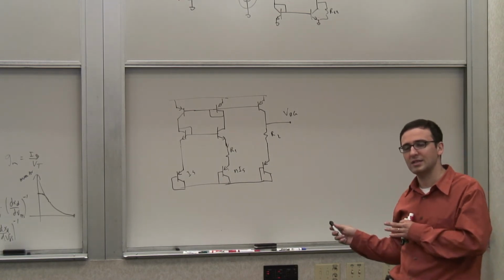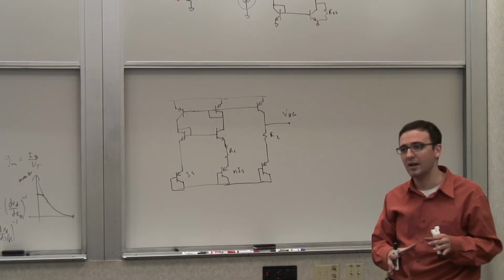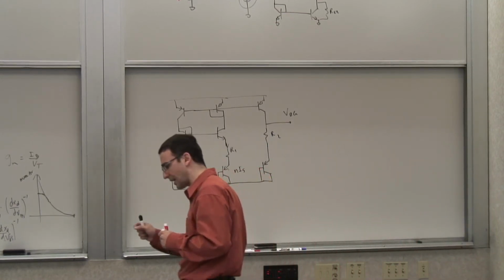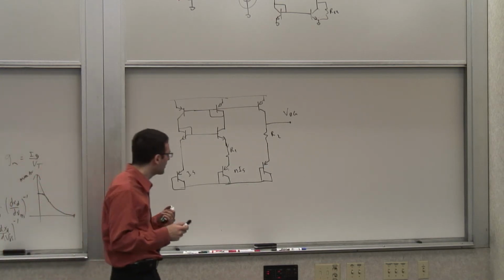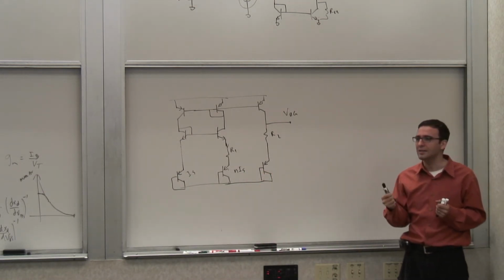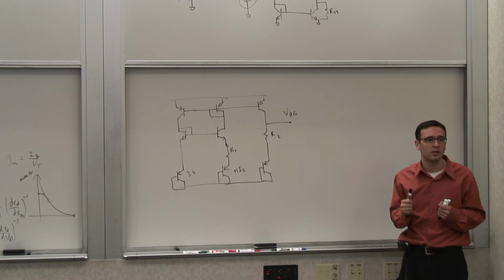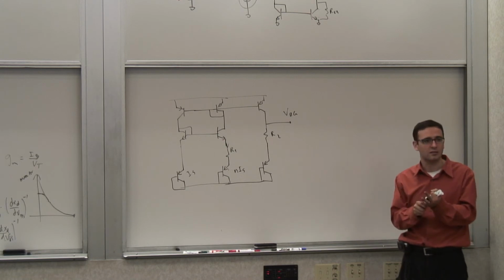We used these different stages that we had and put them together. We saw that in the bipolar case, to get higher gain, you needed to increase the output impedance of that node, maintaining the drive constant, and therefore getting higher gain, but you needed to add additional buffer stages to make sure that you are not loading those high impedance nodes. And we saw that to get the voltage gain, you need a high impedance node, right? So there are two ways to increase the voltage gain in general: the drive and the impedance.